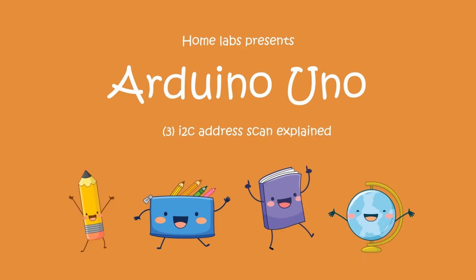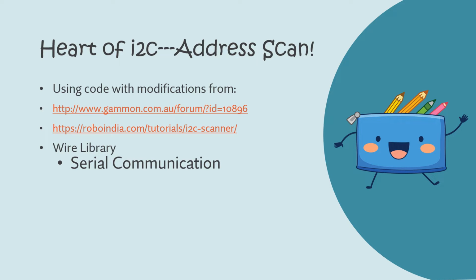So in this tutorial, we'll be looking at code from Nick Gammon. I've taken it from these two websites. The links will be in the description box as well. This code is going to scan the devices connected to the SDA and SCL lines of the Arduino Uno, that is A4 and A5, and print their addresses to the screen. So this enables us to find out the address of the I2C enabled LCD that we are using. And once we know this address, we can use it for our future code.